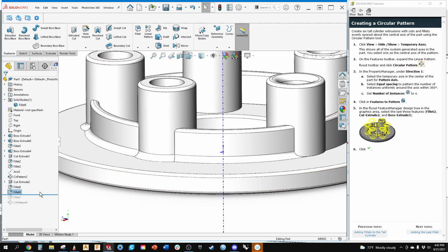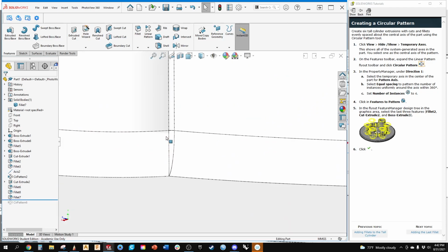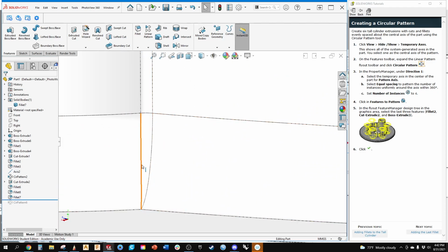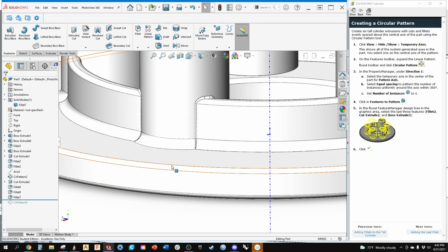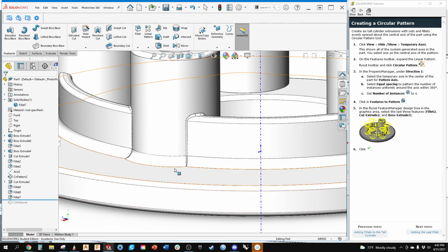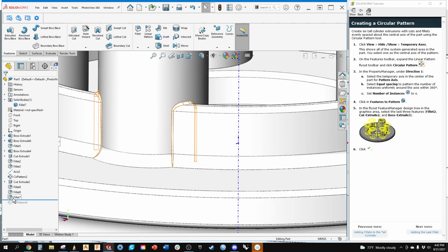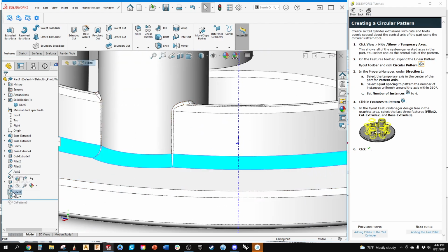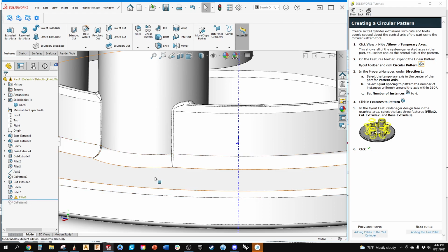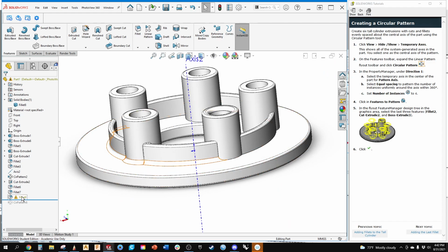Now, I had already put that other radius in there. And you can see if I add that other radius after the fact, again, you get this weird triangle. We'll go over a lot of this later on, how these hit highlights. But I still have to go around to each individual edge. Now, if I move this radius to take place after that, it's going to yell at me. So let's delete it, because I don't know why it wants to yell at me.